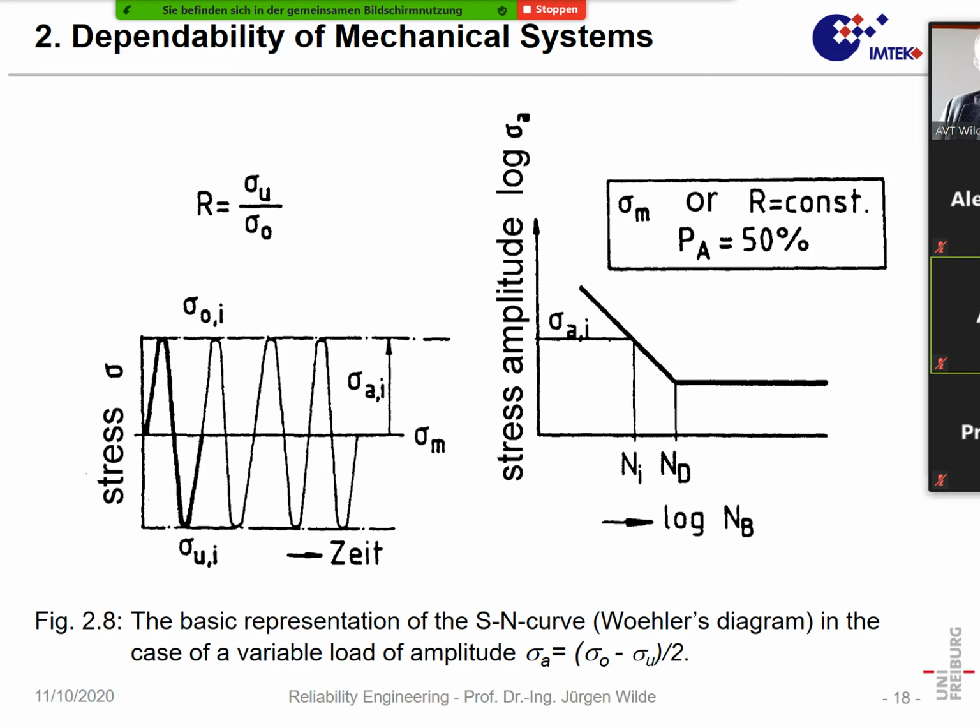stress. We typically can have a lower stress and a higher stress. In the most simple case, it is, for instance, minus 100 megapascal to plus 100, so it's symmetric. But we can also have asymmetric behavior, so we are in the tensile region, so we have a superposition of tension, or we have a superposition of compression.